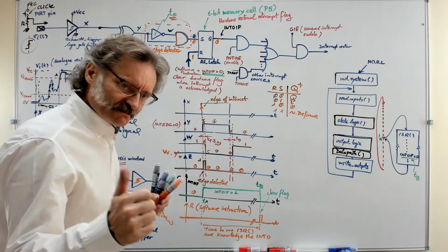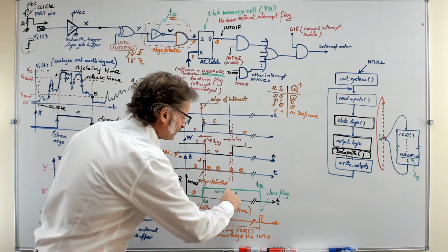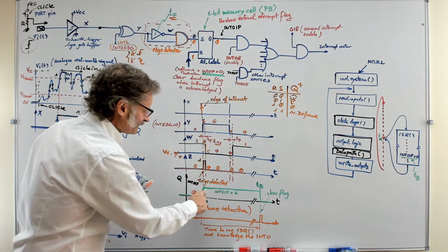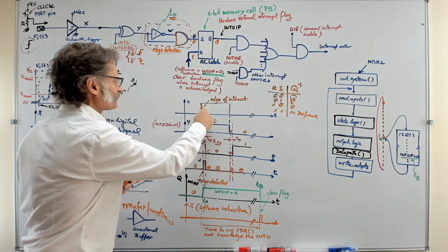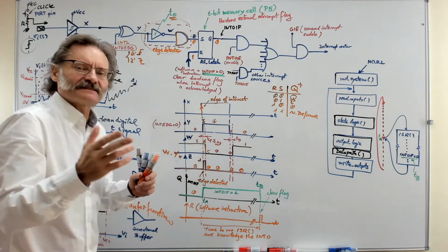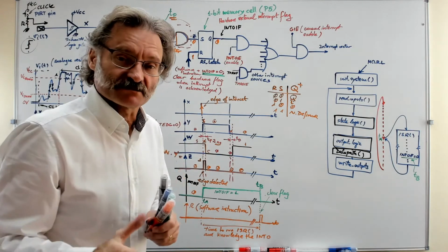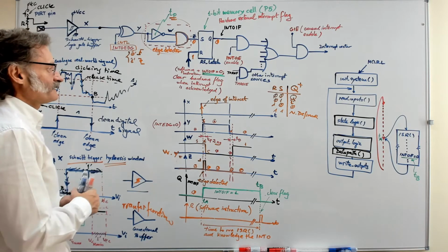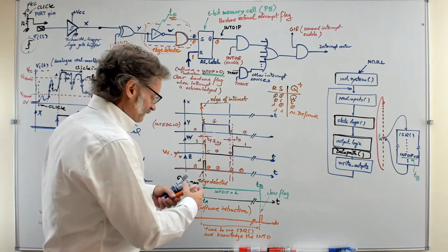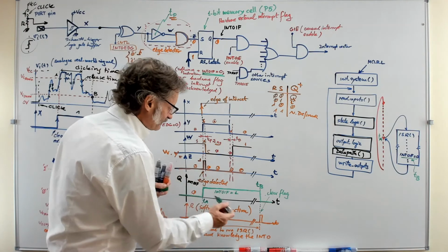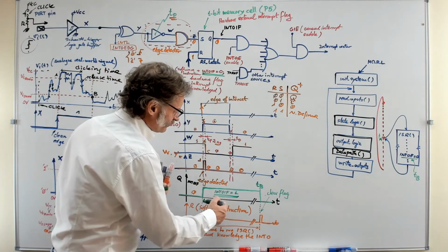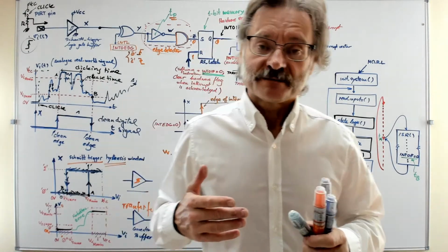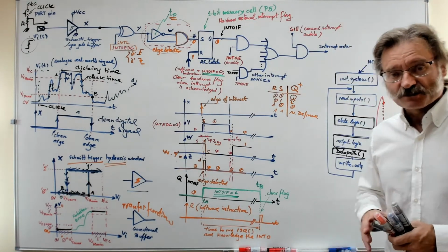So you've been able to save a bit of information that is high ever since the edge has been detected in the X signal. That is the way it works, and this is exactly what you want. And the only thing now, perhaps, to comment is that you can program whether this bit is enabled to generate a vector interruption or not.